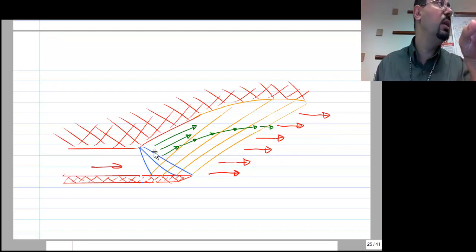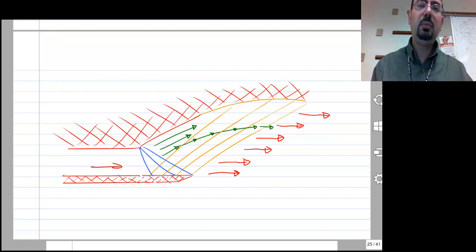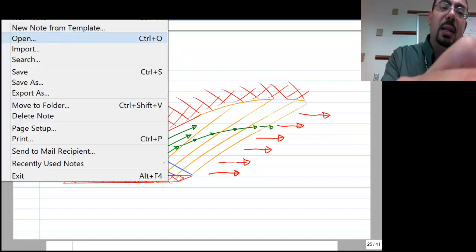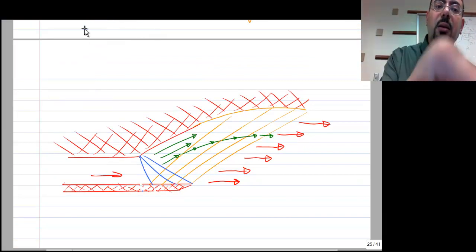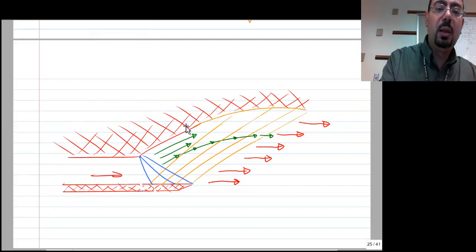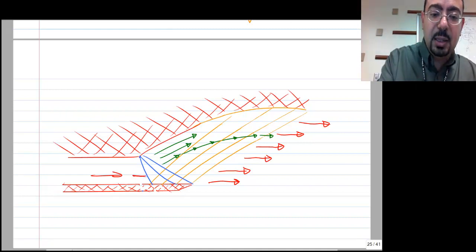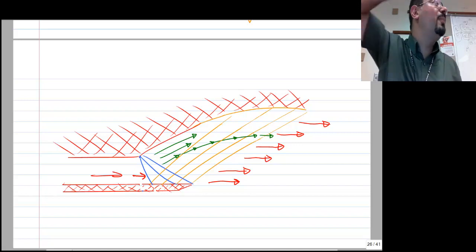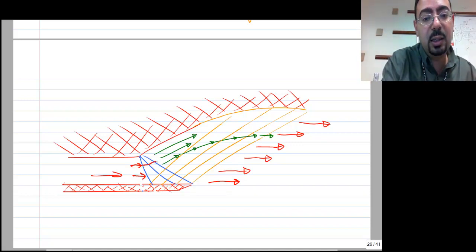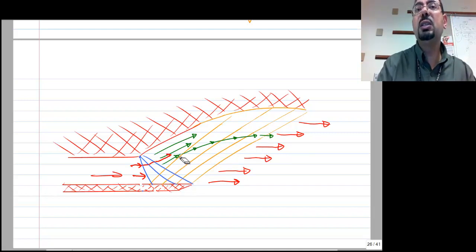But I would like you to look at this, because one year I asked them to plot the velocity vectors inside something like this. So look at that. The expansion fan turns the flow from horizontal to vertical suddenly or gradually? No, gradually. Gradually, right? Unlike the shock wave, where things happen immediately, this one basically goes like this, and then gradually turns into this direction. Because each turn is just a little bit. Excellent. Each one of those rays is a Mach wave, Mach wave, Mach wave. So it's gradually turning like this until it goes this way. So that's why when it reflects, it also does not turn you immediately horizontal. With each one of them, you gradually straighten up until you leave horizontal.